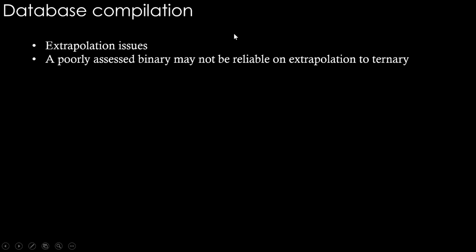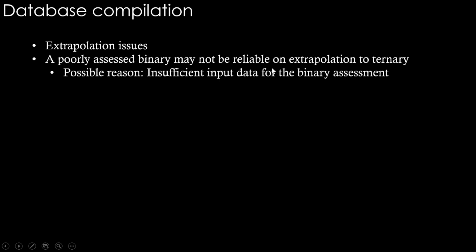In extrapolation there can be some issues. A poorly assessed binary may not be reliable on extrapolation to a ternary. Why? Because of insufficient input data for the binary assessment. The binary assessment doesn't have a lot of points. Very scarce points are available and somehow the fitting is done, and the fitting can be done with different sets of parameters. All of them can reproduce these experimental scattered points. But will they be able to do the extrapolation right? That's where the problem comes.